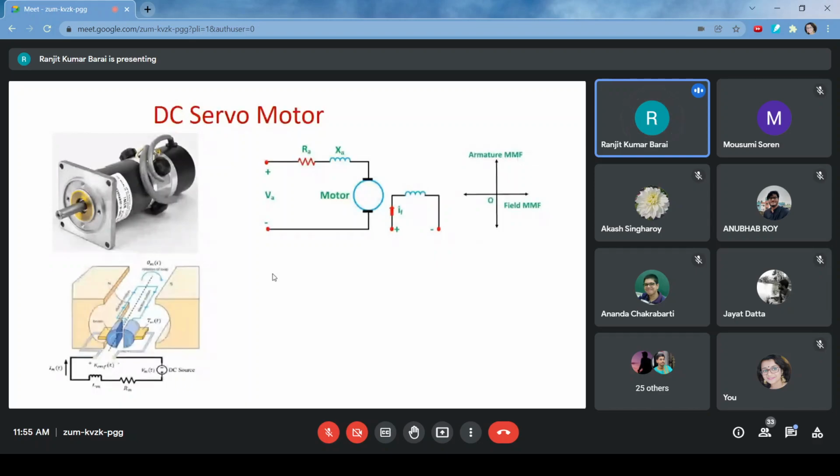So during the magnetic circuit design, we should select the nominal value of the flux density, so that variation of the armature voltage does not force the actual operating point of the flux density to penetrate into the non-linear region.